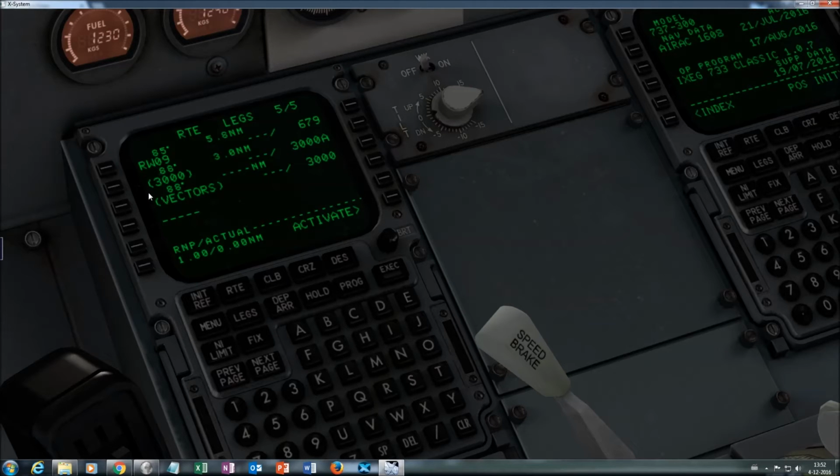We have checked if all the legs in between are correct and if they are all connected to each other, that there are no discontinuities, because a route discontinuity means that there is a gap in your flight plan, that you say I want to fly to position Y and then I want to fly to B, but the 'then' has gone. I hope that's clear. You will sometimes get them, so you have to be especially careful when you insert departure or arrival routes. But we have programmed it now and they are not there, so that's good.